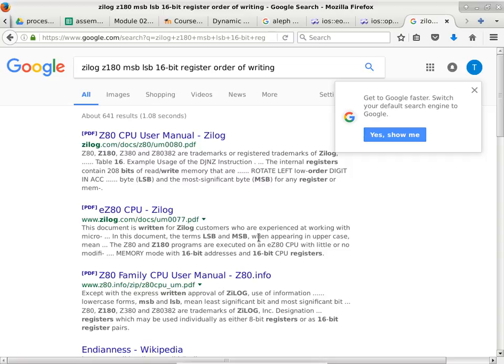So that's why I just want to give you an example of what race conditions can do. It can make the product seem like it's working, even though it is just marginally working in the right direction. But as soon as you change little things in the process, in the die, in the transistor size, the problem will show up. So if you're going into computer engineering or electrical engineering, you want to eliminate race conditions. And if you cannot eliminate race conditions, you need to let people know, so that people can use other means in software to get around a potential of getting into race conditions.